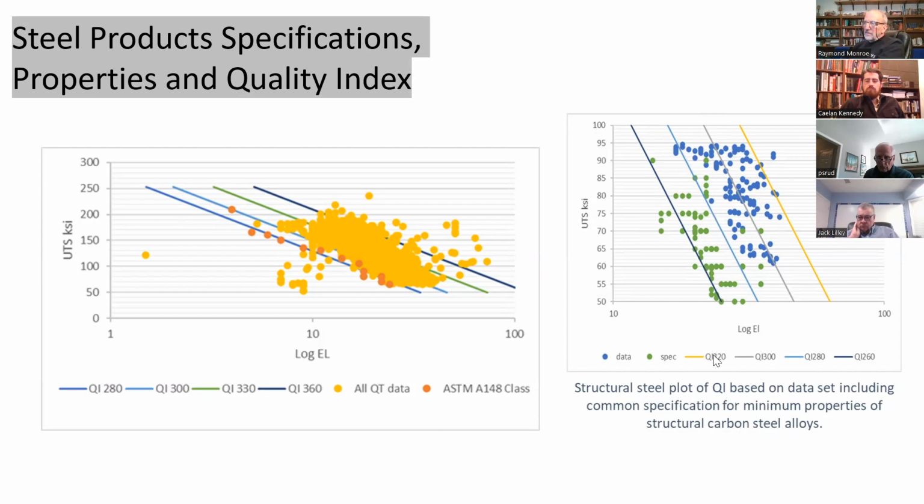And then I got a bunch of data sets, and these are mill products, properties from the data set. And you can see that even though we didn't know it when we set all those specification limits, they are at the lower bound, and they're generally around 280 is the lower bound. It turns out that 280 is a good number for castings too.